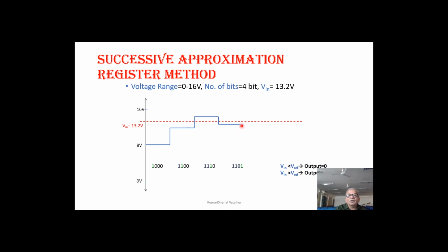You don't have more resolution, because take the example of a foot rule which is marked with centimeters. Every centimeter there is a marking, and between 2 centimeters, 4 and 5 centimeters, there are 10 markings of 1 millimeter each. So you can say either 4 centimeters and 3 millimeters, or you can say 4 centimeters and 4 millimeters. You cannot say 3.1 millimeters. That is not possible. That is wrong, because your marking is not available. So you use a vernier, a more accurate thing, you may increase 1 bit. If you take 100 readings and take the average, you may increase 1 bit.